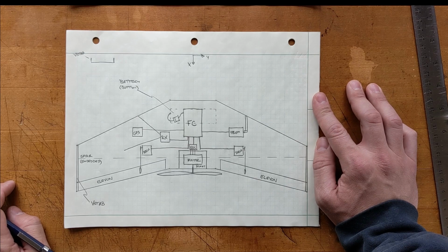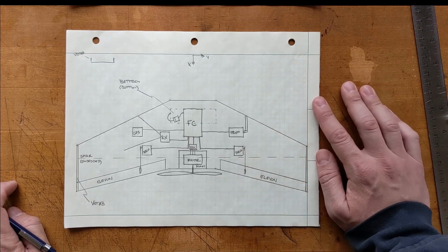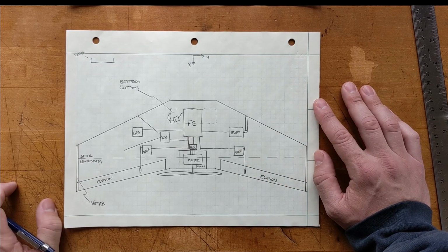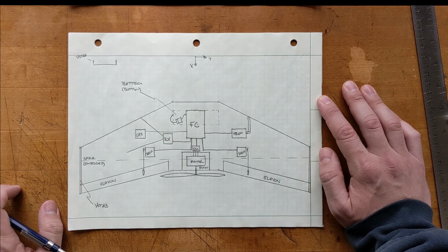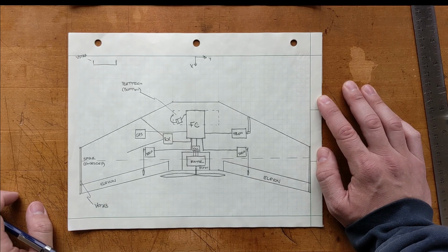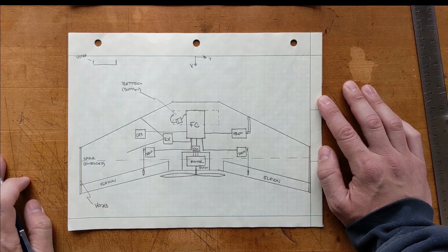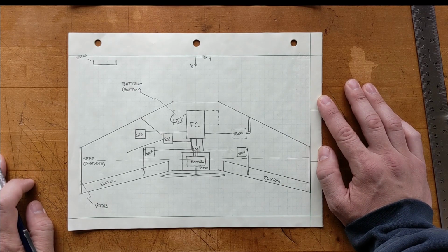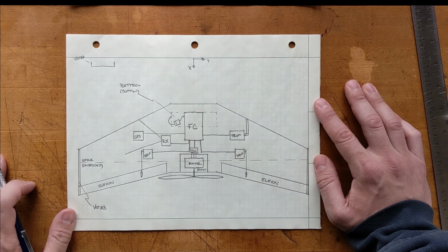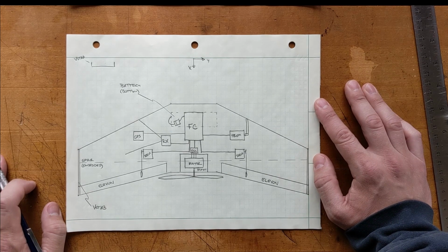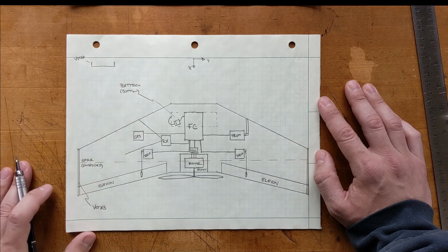a high-def video recording. So one way to accomplish this would be dedicating specific cameras to each of those tasks. Now, from quadrotors and all kinds of other aircraft, there's a lot of FPV cameras that are available, and what they often do to get nice video to record for later is mount like a GoPro or something like that. But honestly, again, our sub 250 requirement is going to dominate our decision making, and so we need to find something that can do both of those tasks, and those are often called split type cameras. And what it does is it functions both for FPV video and it saves HD video on board.